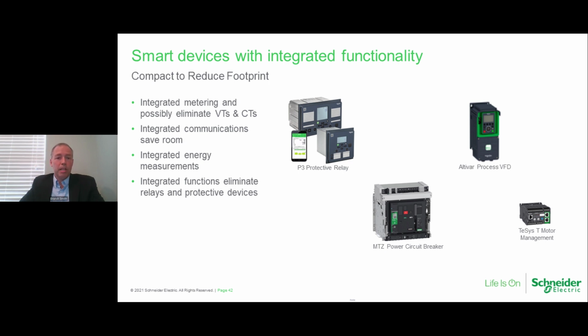Also, we have the ability to integrate a lot of functionality into the devices. If you look at the protective relays we have had for years, it essentially is a PLC in addition to a protective relay. So we have the ability to move a lot of the controls and a lot of the automation into the device itself, not only saving the cost of additional equipment needing to be installed, but also sometimes all the extra equipment drives up space.